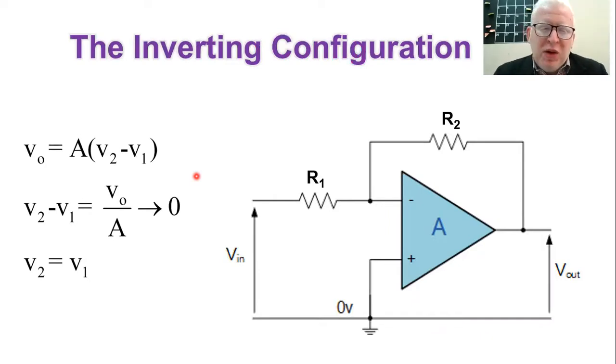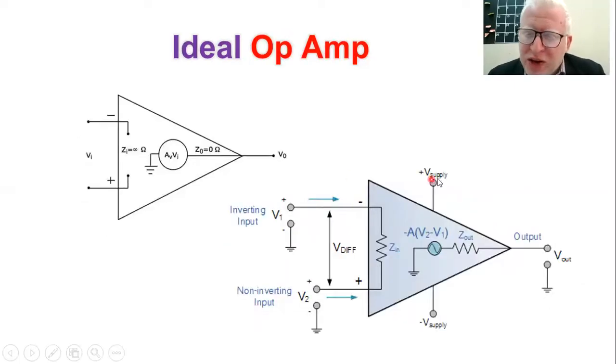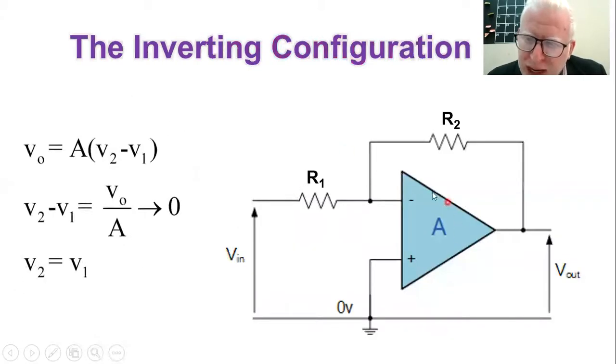Now, we discussed together in the previous lecture this circuit, which is a closed loop circuit. We distinguished between it and what's called an open loop configuration, where there is no feedback branch between the output and the input. Now we have a feedback branch between the output and the input with the resistance here called R2, connected to the inverting terminal of the input.